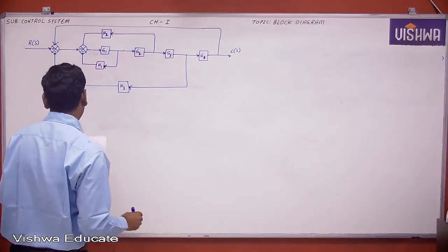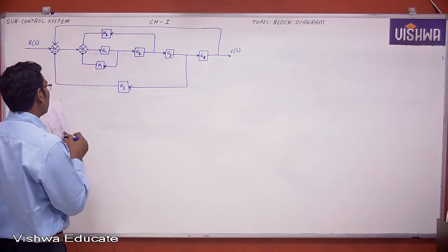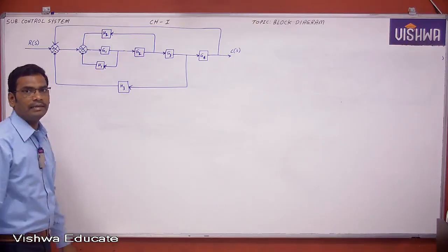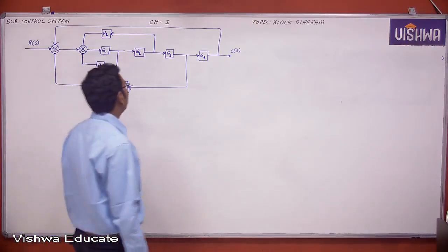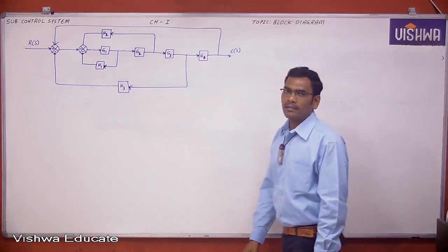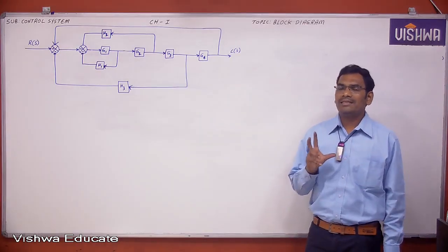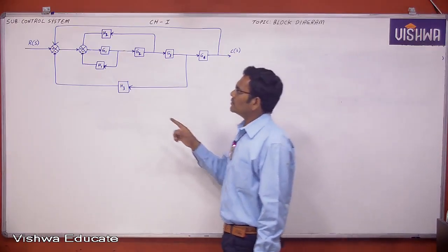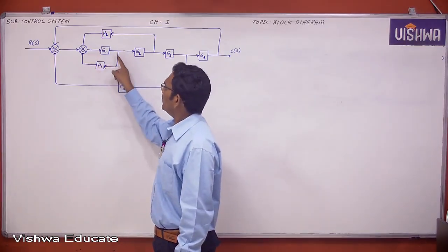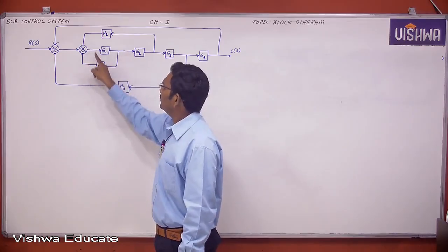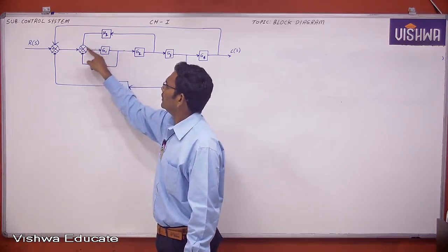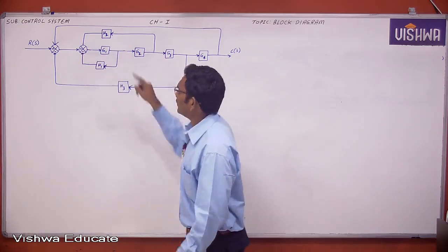Now see here. This is the block diagram which is given to you. First he is asking to find the transfer function. Now what should you do? You just tell me first. First you see whether there are any positive feedback or negative feedback terms. Now see here, this is the forward path gain, this is the feedback path gain. Now are the summing points and all these things removed or not, first immediately? If you do like that, this summing point and all these things are removed.